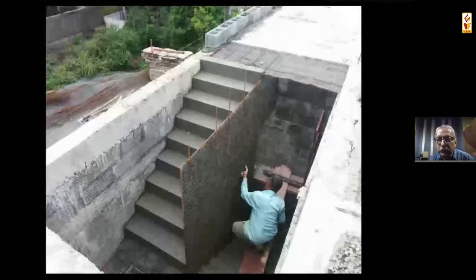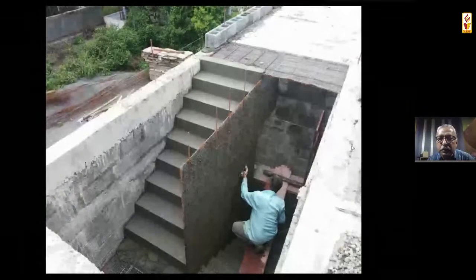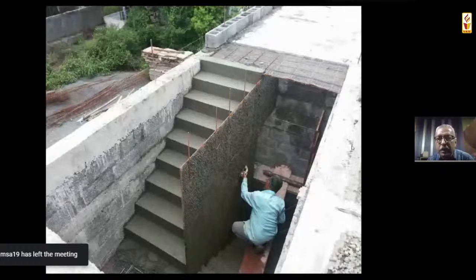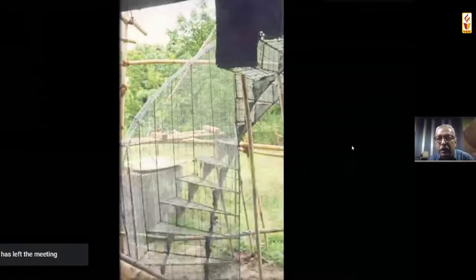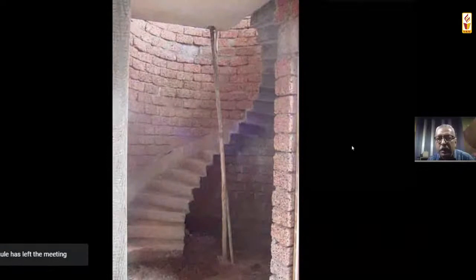And because of that, what happens, and outside also sometimes if the client agrees, then we rub the joints of concrete blocks with special waterproofing glue, and then after that we just paint it. Otherwise you can do that Ahmedabad Dabba plaster, which is hardly 3 mm thick. So all these kinds of forms are possible in ferrocement, which otherwise we kill on our drawing board, because centering for this kind of work will be very expensive because it will be just one-time use.